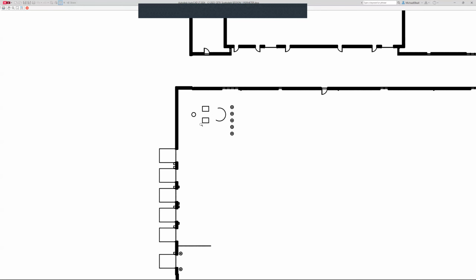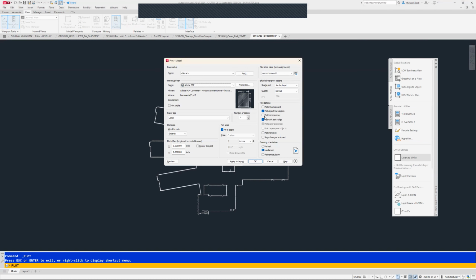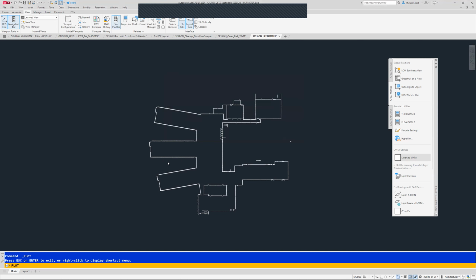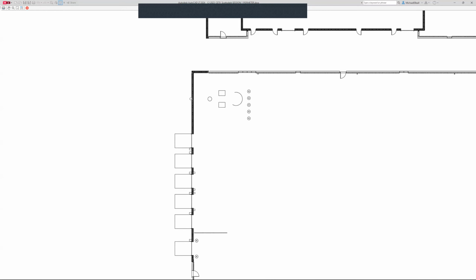One other thing I want to share with you though, you ever go to plot and even when you do the PDF, the lines look like they've been drawn with a Sharpie. Okay. Little note, don't plot line weights. So you set no plot line weights and you click your preview now and you go in there and you have very, very crispy features in here.